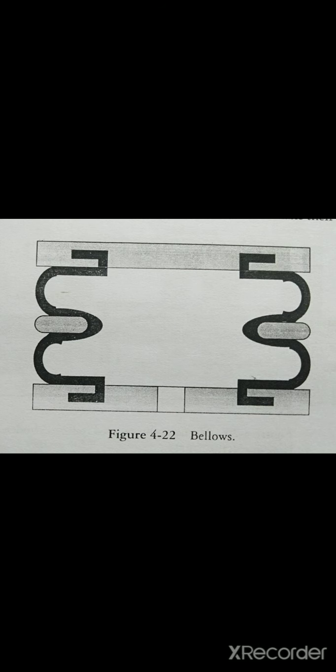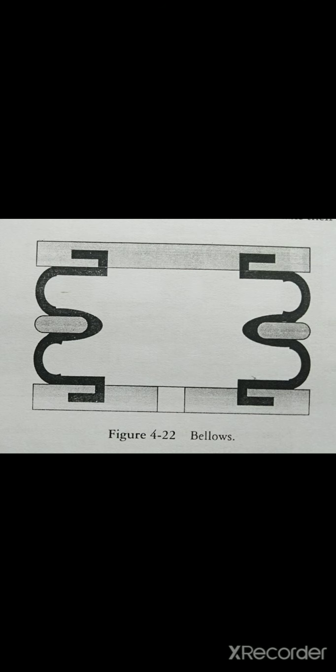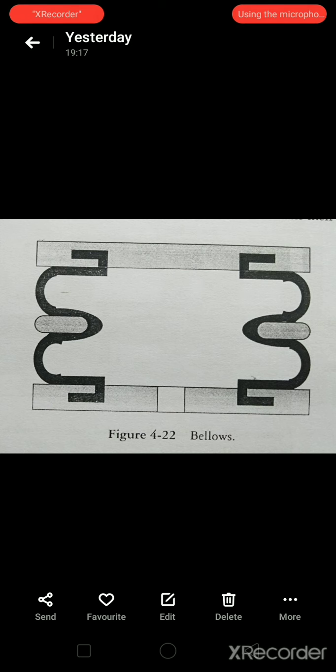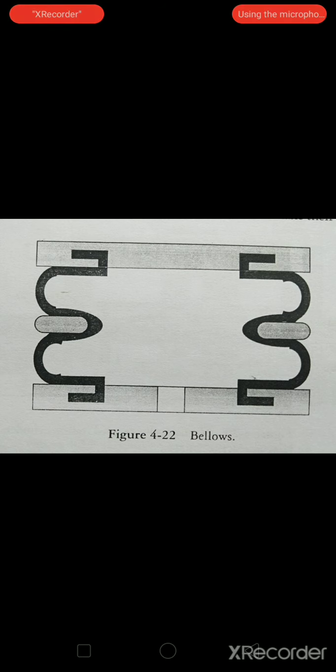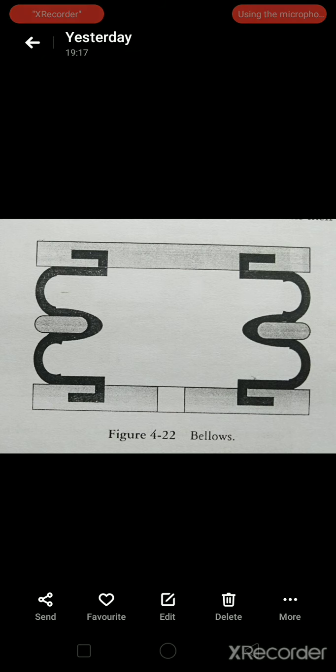The bellows actuators are designed to function efficiently and economically in the harshest environment. These are available with plastic end plates for lightweight and corrosion resistant application. The versatile air bellows can be used to solve a large number of problems experienced by the engineering industry. Standard bellows actuator models are manufactured with a nominal diameter in the range from 8 inches up to 15 inches with 1, 2 or 3 convolutions and stroke length in the range of 80 to 380 mm.